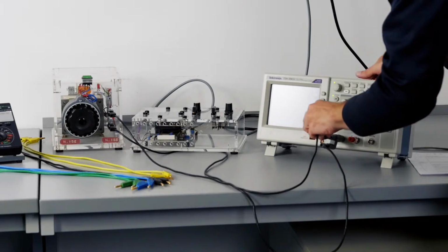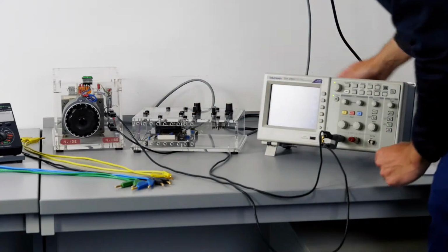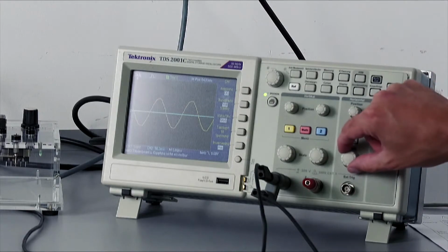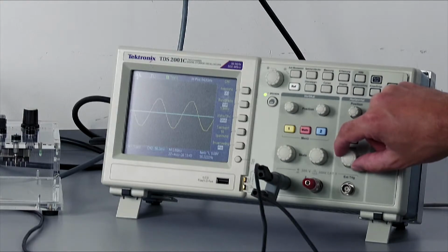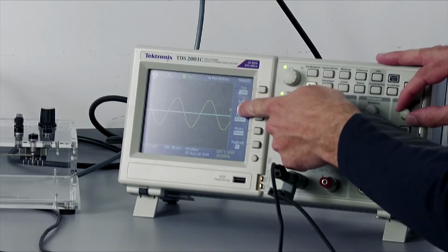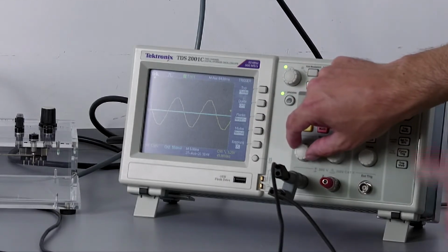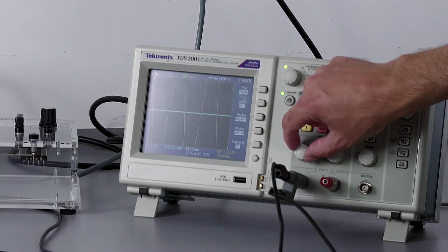Connect the input of the oscilloscope to the power supply unit and display a sinusoidal alternating voltage on the screen of the oscilloscope. Then observe the screen with different settings of the oscilloscope, e.g., varying the time resolution, the trigger level, the polarity of the trigger slope in the trigger menu, or the measuring range of the voltage.